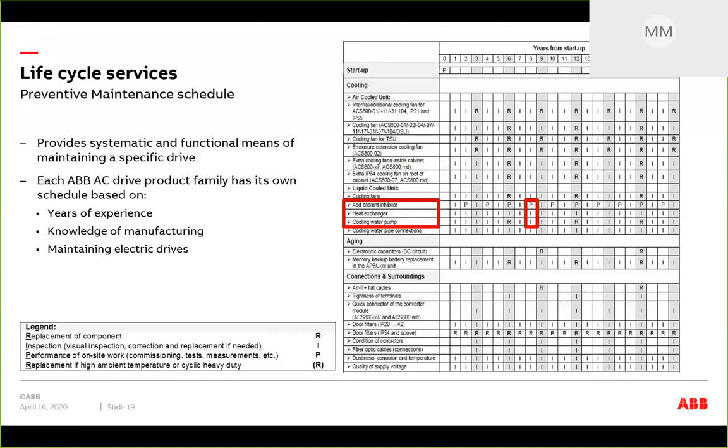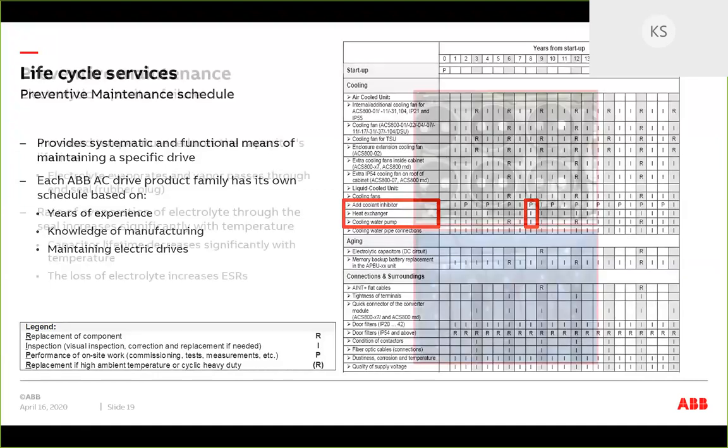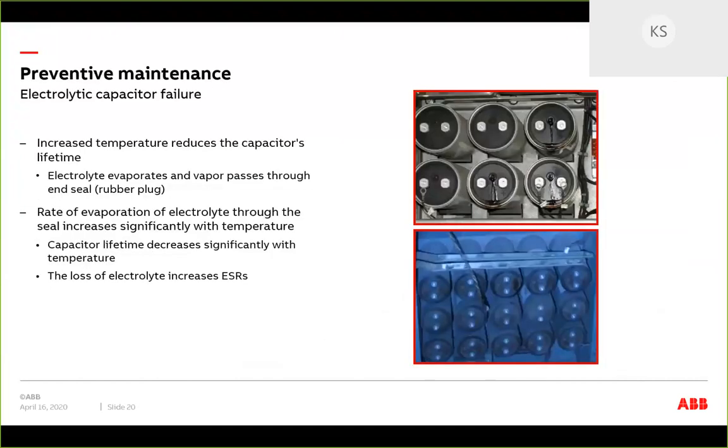And we're going to show you some pictures. I see in the legend there's RIP, rest in peace. If you don't do this, maybe that's where your drive ends up. Just Kevin humor. But these are some pictures of real stuff. And Matt mentioned some capacitors. If you look at your capacitor banks and they've got stuff oozing out of them, you have probably waited a little too long.